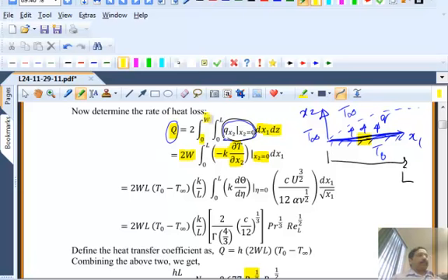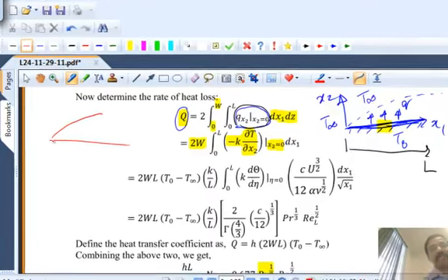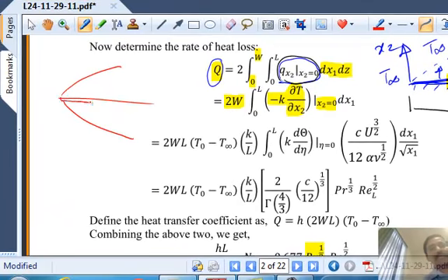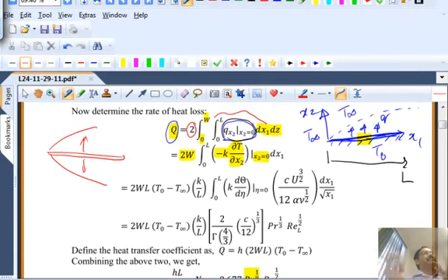Top, so you're maintaining, in fact, if you remember the figure from the last lecture in your book, he had a boundary layer going that side and a boundary layer going that side. And this plate is maintained at a constant temperature. So from the plate, you are having heat flux to both sides. Okay, and that's why you get the 2. And 0 to W, none of the quantities in this expression depend on W. So 0 to W dz simply becomes W.